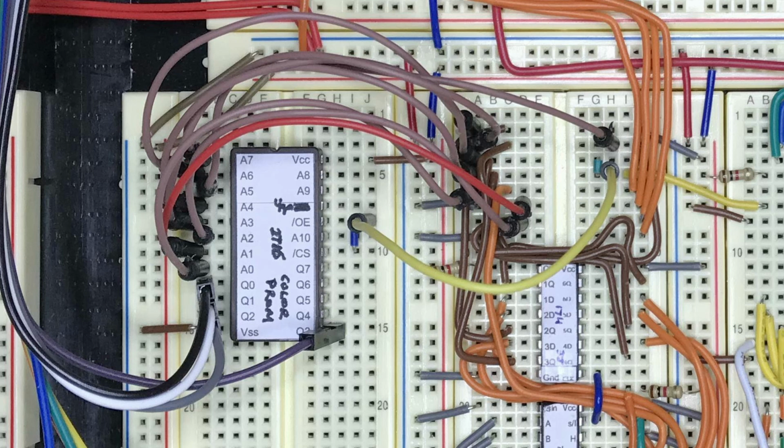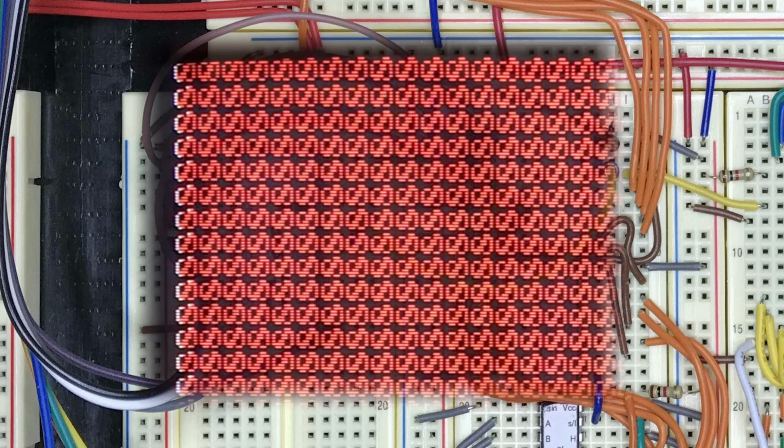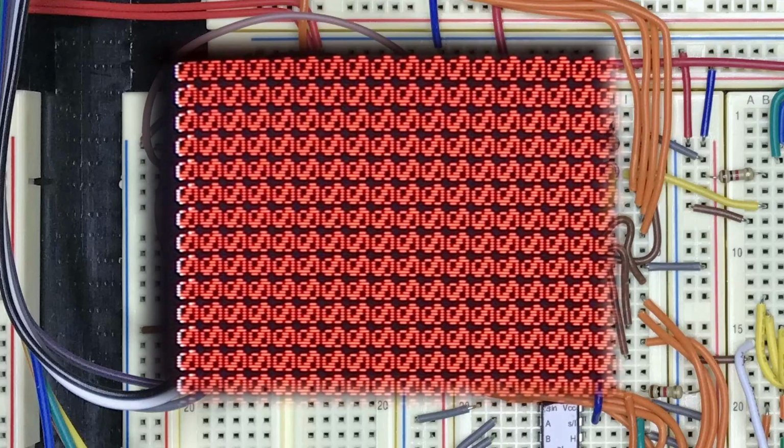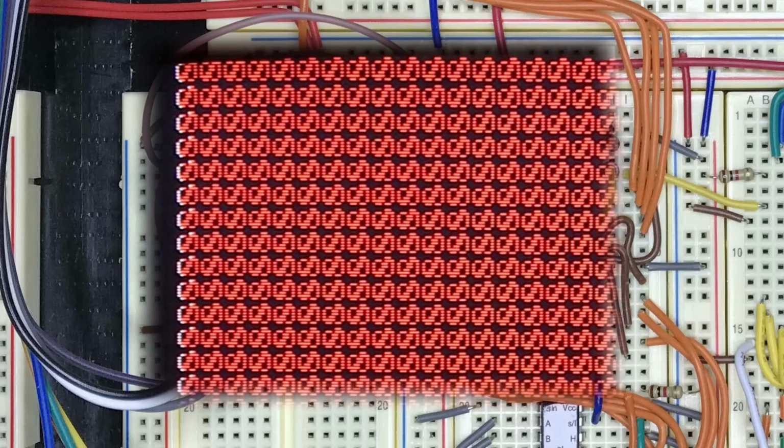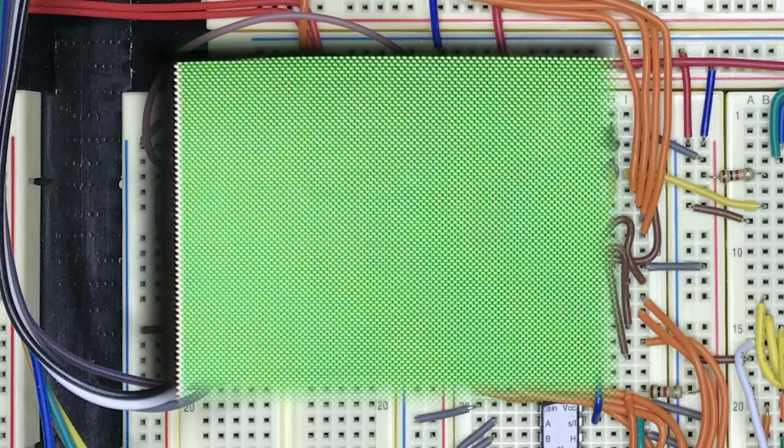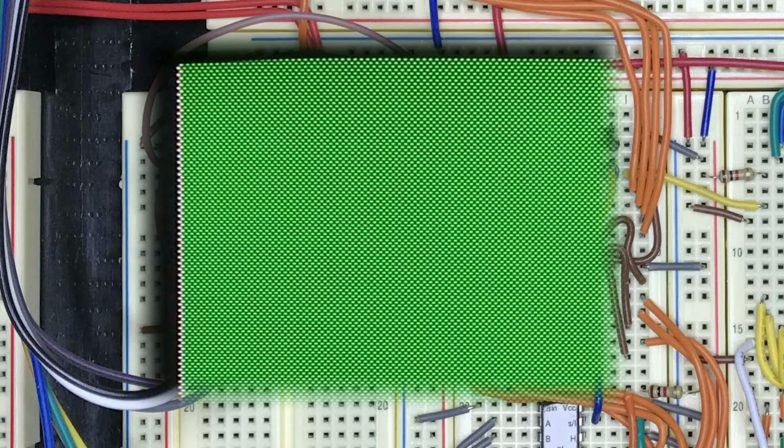To do that, I burned the color PROM hex data to the lower part of the 2716 ROM and left the rest blank. You can see here I've removed the other color PROM and connected jumper wires to the 2716 test color PROM. When we power on the breadboard, we do get a successful image. There are a few small artifacts at the leftmost edge of the screen. I suspect the typical color PROMs may work a little faster, and that's one of the reasons why they're used. For now though, to prove our system, I think this is a satisfactory solution.